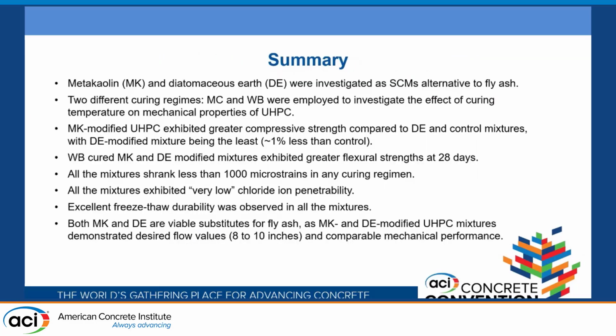So these are the conclusions. Metakaolin and Diatomaceous Earth were investigated as alternative cementitious materials to fly ash. Two curing regimens were investigated. MK modified UHPC had greater compressive strength when compared to the control, and DE-modified UHPCs showed similar results as control, within approximately 1%.